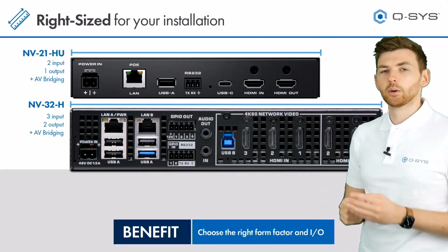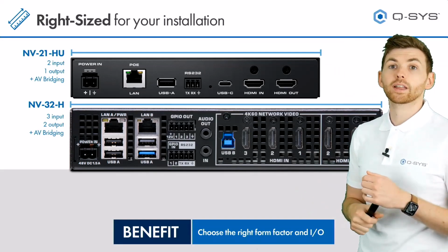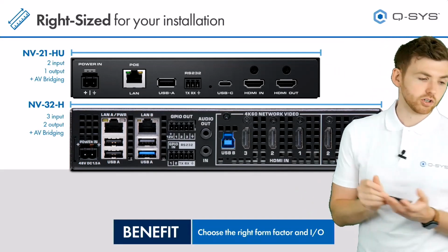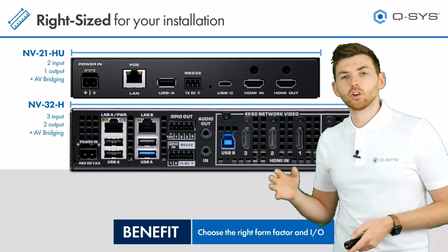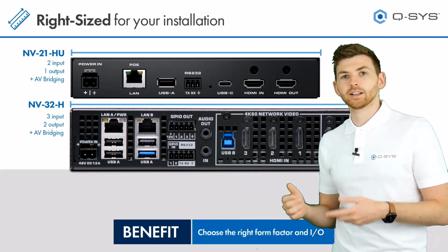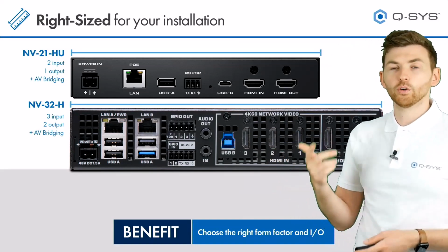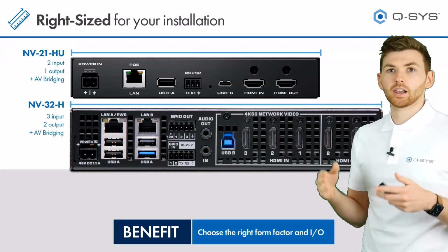Have a question here about video formats. Does the HDMI output do 4K 30 or 4K 60? It's up to 4K 60. Good question. Also, the encoding and decoding on this is not like JPEG 2000 or one of the more lower quality codecs. It's always 444 chroma subsampling. Okay, so there's no subsampling of the color at all.